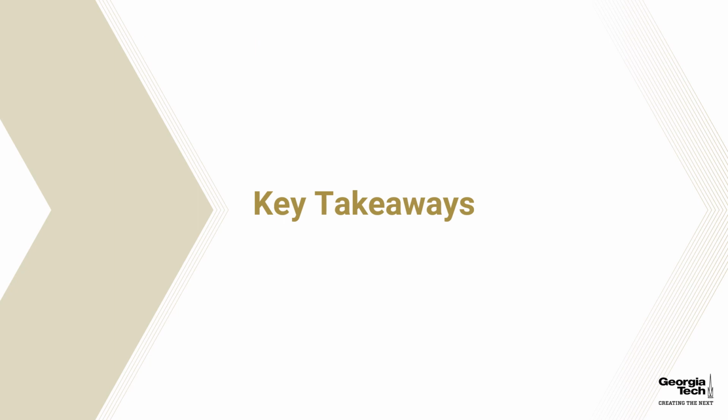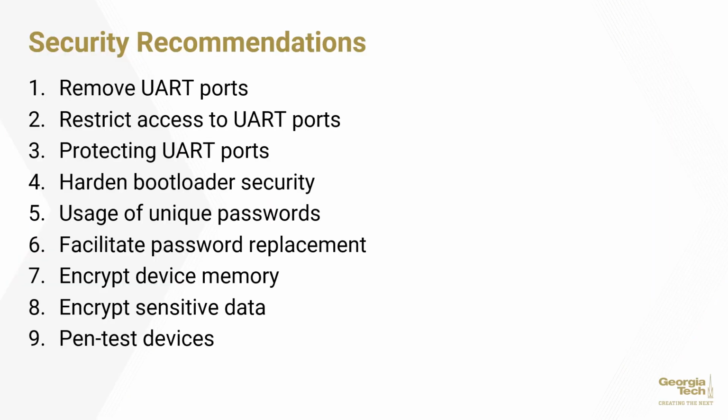Finally, we can talk about the key takeaways of this paper, which happens to be how to avoid someone easily reverse engineering your IoT product. So we've got a list of security recommendations, which shouldn't be a surprise at this point, since all of these were used in the reverse engineering methodology. First, we should remove any unnecessary UART ports whenever possible. If they are necessary, then you can restrict access to them by making them read-only. And then finally, if they need to be write-enabled, we can still protect the UART ports in a similar fashion